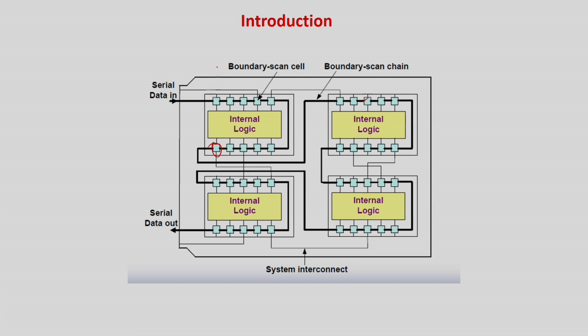Maybe I can tell you that these are your external pins, these are your external pins, these are the external pins. Problems are with this internal world. How to access it? So again, very famous old story, scan chain is going to help you. So what is a scan chain?